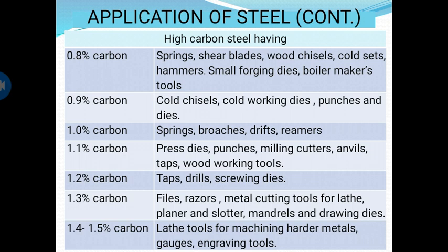With 0.9% carbon, it is used for cold chisels, cold working dies, punches and dies. With 1% carbon, springs, broaches, drifts, reamers.